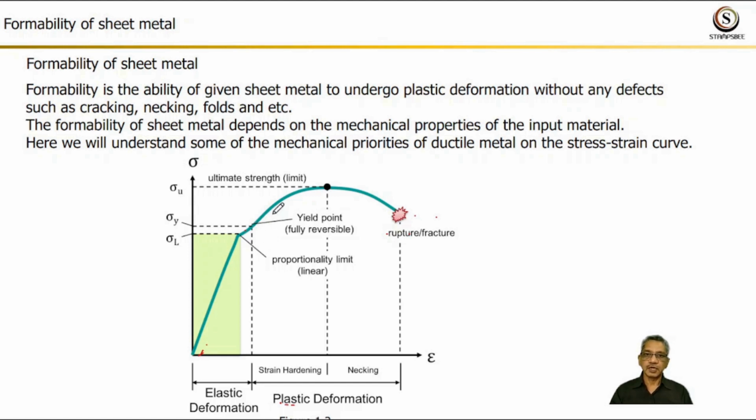The curve from the yield point to the ultimate strain point shows that stress is increasing drastically with less increase in strain. Changes in dimensions are not reversible after removal of the load. The curve from the ultimate strain point to the rupture point shows that stress is not increasing but strain is increasing radically in this zone. At a particular point, the material ruptures.